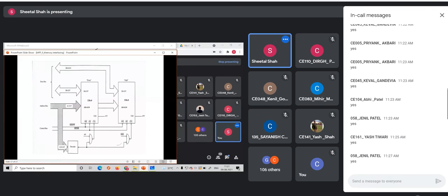Then a decoder IC is required, so A16 to A19 can be the input to this decoder IC. As we know, only one of the outputs of the decoder would be high, if I am considering that we are having an active high output. Whereas here, since it is shown with a bubble, that means only one of the outputs is zero, whereas the rest of all would be ones. Are you getting this? That means the decoder has an active low output.